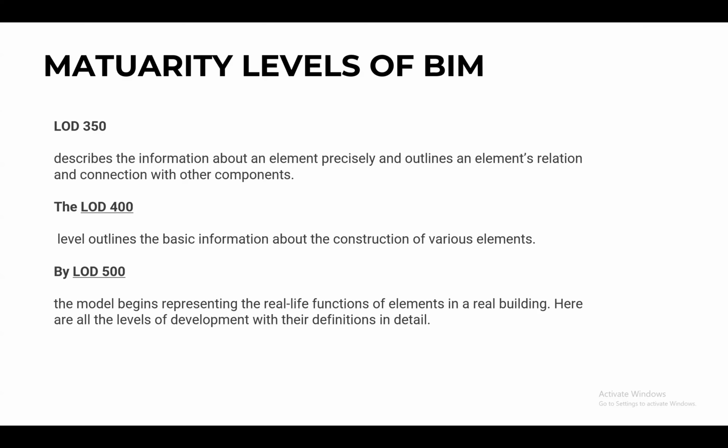And LOD 350. In LOD 350, you can get precise information of the model, and you can get connectivity between structural elements and MEP elements. So you can do clash detection in LOD 350 because you can identify the connectivity between different departments. You can have a building model and an MEP model, merge them together, and detect the clashes because you can find the connectivity between those two departments.